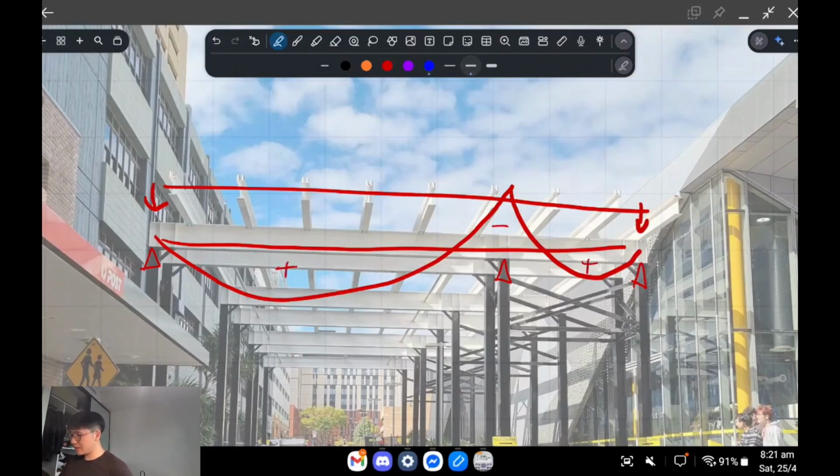And because we've put the bending moment on the bottom side where it's got positive bending, this is an indication of what the tension flange will be. And so the opposite side, the compression flange, is our critical flange whenever we've got beams that are supported on both sides, so not cantilevers.